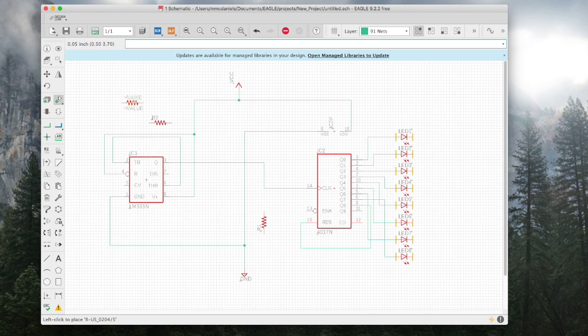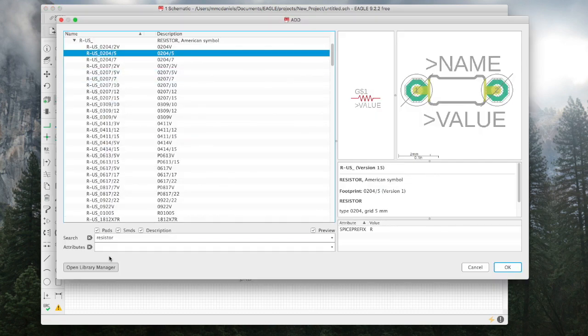So here we're placing the resistors and doing the necessary wiring to move forward and build the circuit. So we want to make sure we get our circuit design correct first. And one of the interesting things with the 4017 and the 555, you can power it to 15 volts. So I decided to use a 9-volt battery because it's convenient.